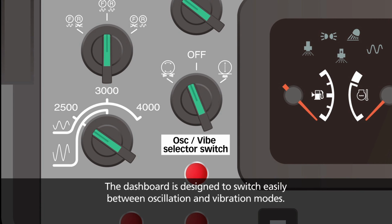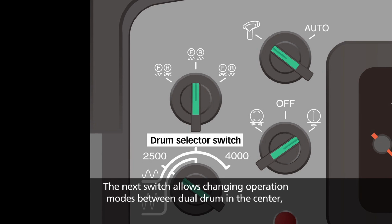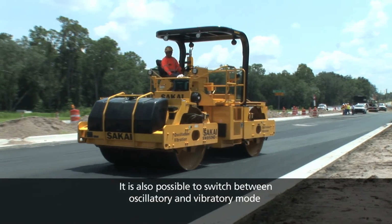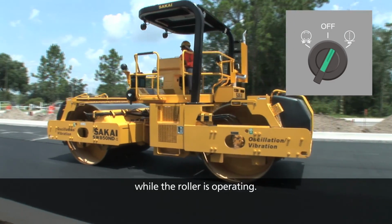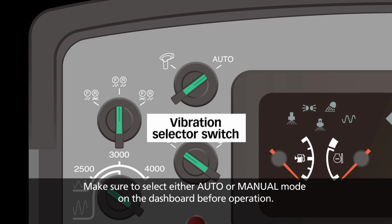The dashboard is designed to switch easily between oscillation and vibration modes. The next switch allows changing operation modes between dual drum in the center, front drum only on the left, and rear drum only on the right. It is also possible to switch between oscillatory and vibratory mode while the roller is operating. Make sure to select either auto or manual mode on the dashboard before operation.